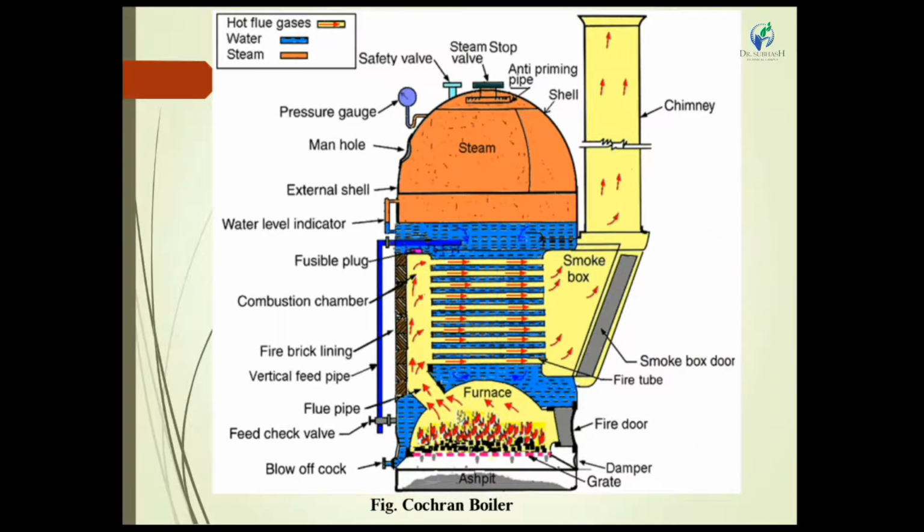The steam formed from the water is collected in the steam drum or hemispherical drum. Then it creates a pressure rise because the volume is constant. The collected steam is passed out from the steam stop valve for further utilization. In case a heavy critical pressure is created in the boiler, the safety valve operates and lets the steam out from the boiler.